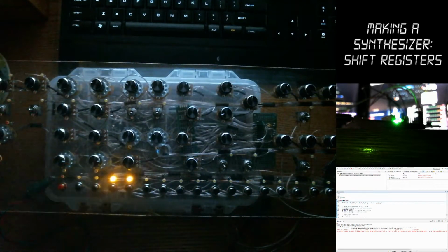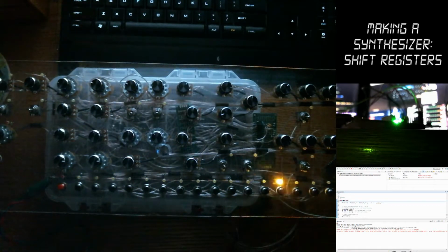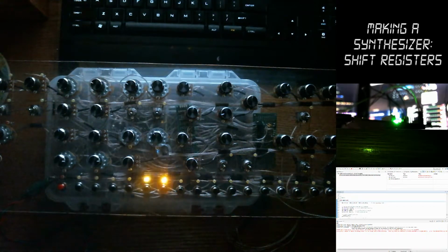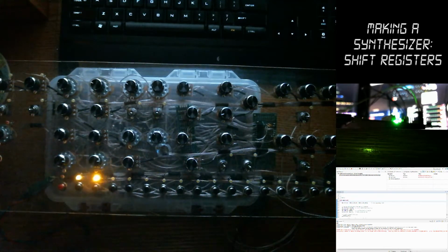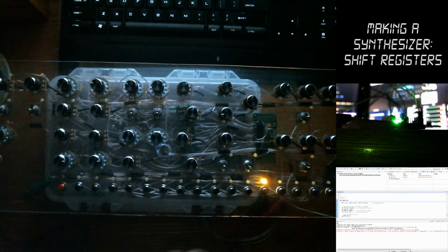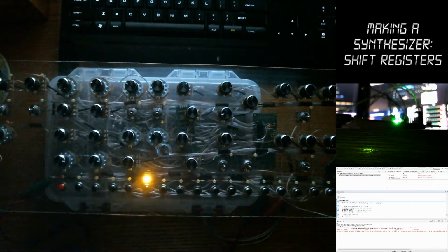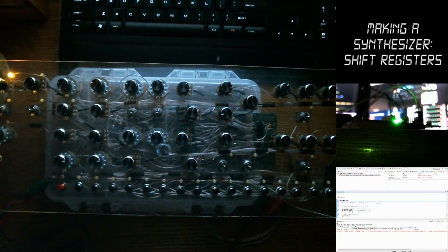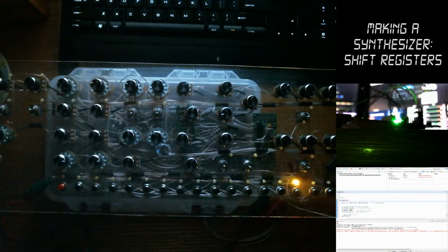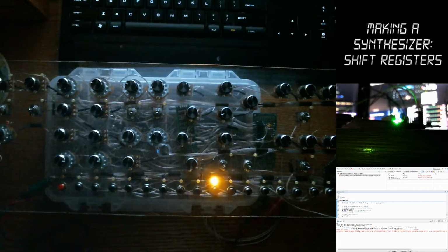But yeah, that's shift registers. You can use them for a number of different things. One is if you have a low frequency digital to analog converter that you're using. I mean, maybe it's 1 kilohertz or 20 kilohertz or something, then you could get away with using shift registers to access the inputs to a digital to analog converter if it doesn't already have some sort of shift register in it.